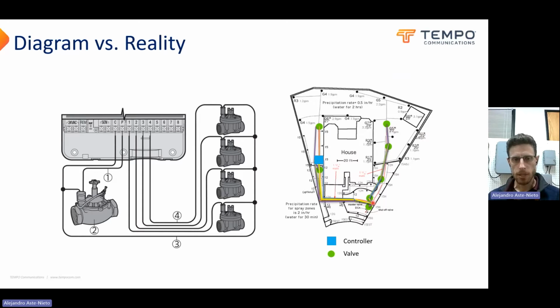But that common wire has to meet up with this valve here, and this valve will be using the common wire as well. So even all these little sections between the valves that have a white wire, we consider that the common wire, even though it's not one continuous piece of wire. It has to splice in with all these valves.